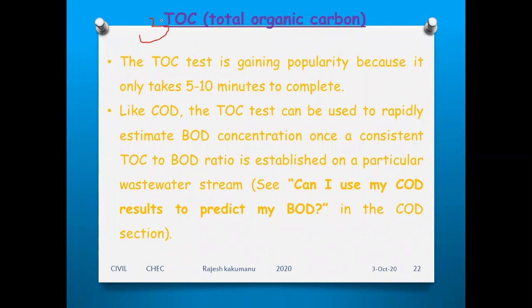Like CBOD, the TOC test can be used to rapidly estimate BOD concentration once a consistent TOC to BOD ratio is established on a particular wastewater stream.